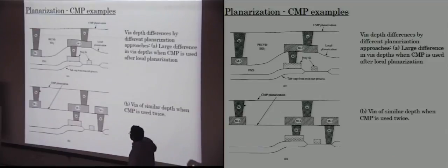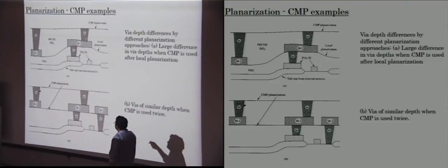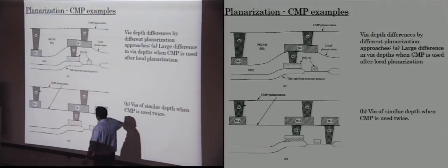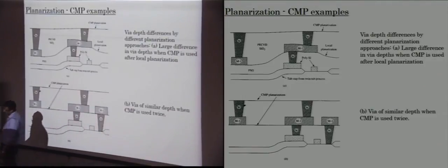Similarly, when you are filling, let's say you're using CVD to fill tungsten within this via and within this via, of course this via would get filled up very quickly. So it is better to do planarization at the early stage itself, such that you have more control over the processes that you want to utilize. So don't try to do it halfway, do it early.